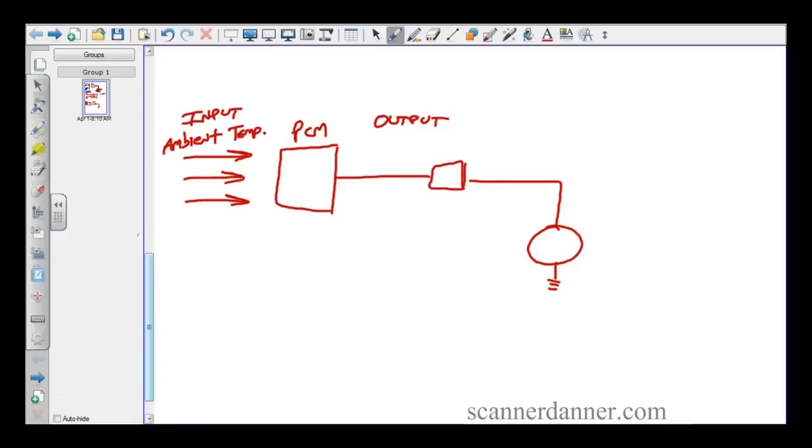These are done with pressure sensors too. If the temperature's too low, the pressure's too low, and it's really pressure that won't turn the clutch on, but we can say ambient temperature. I like that. Same thing, you're saying, the amount of refrigerant. Now we're talking about pressure. Let's throw that in there. AC pressure or system pressure. And again, we'll keep this generic. We don't have to be specific on the inputs, but that would certainly be another one.